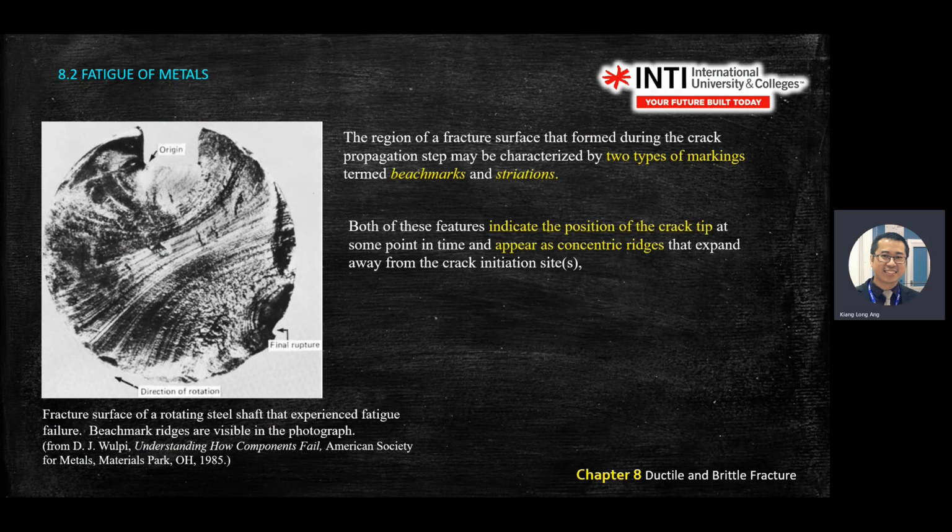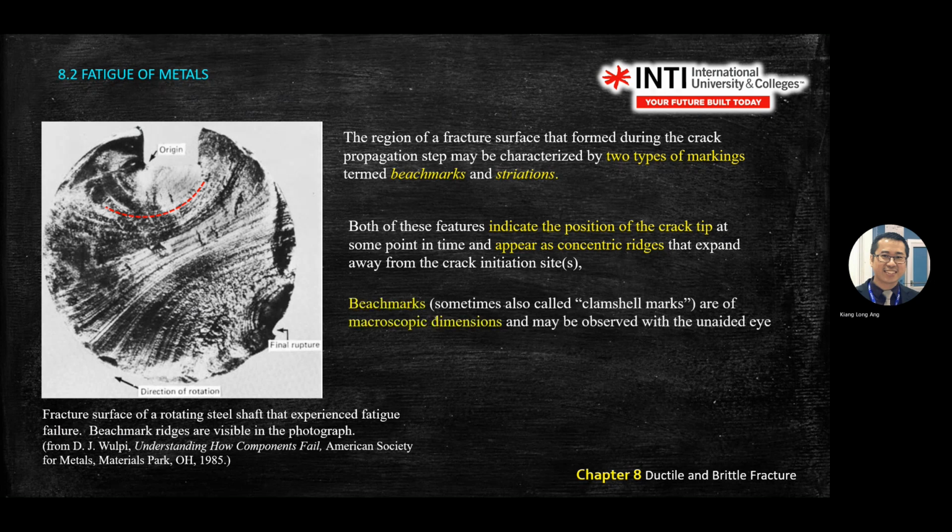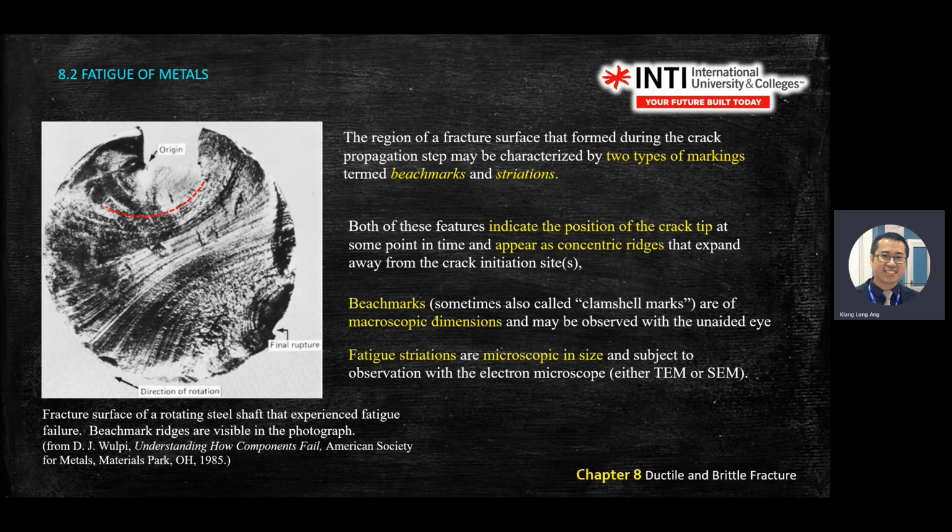The rest you read. So there are two: one is beach marks, one is striations. Beach marks you can see very clearly, like a shell mark, with your naked eyes.